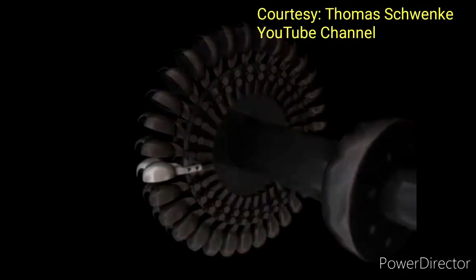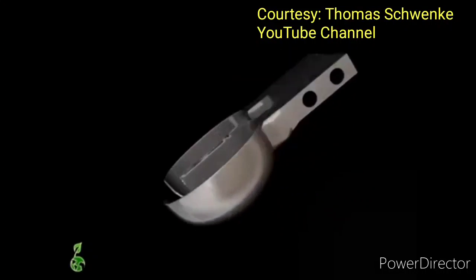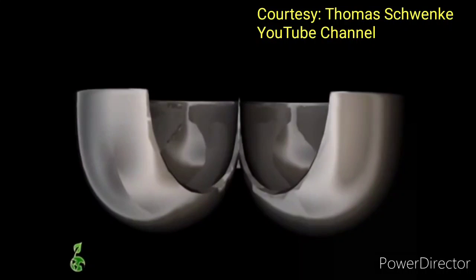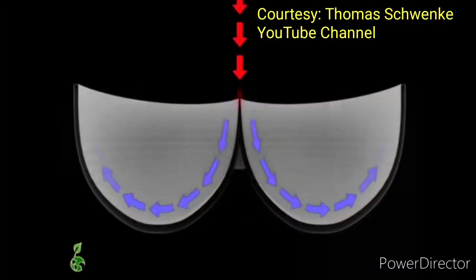A series of spoon-shaped buckets is mounted around the edge of the Pelton wheel. Buckets are usually cast as one solid piece, which is necessary to avoid damage, such as fatigue failure. The buckets have splitters placed at the middle of them that divide the water jets into 2 equal streams.